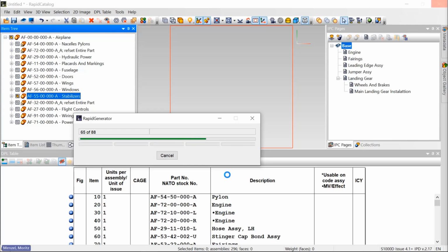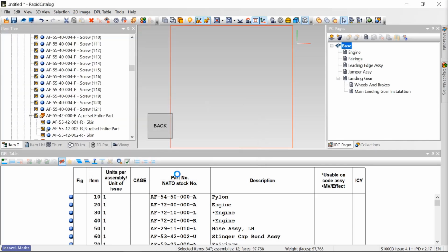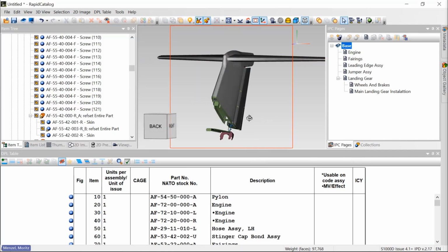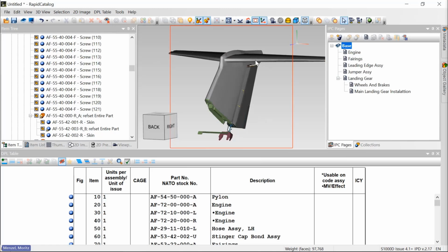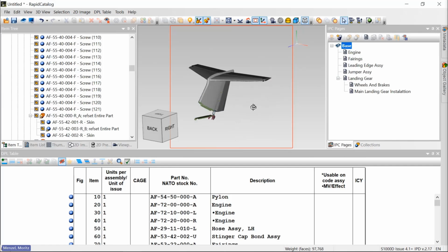Incremental import also recognizes items imported into the project from different source files with different import profiles and will handle this case correctly. As a final note, this feature only works with a limited number of formats, more specifically JT via RapidJT component, CATIA, ProEngineer, NX, and SolidWorks. More information you can, as always, find in our documentation.